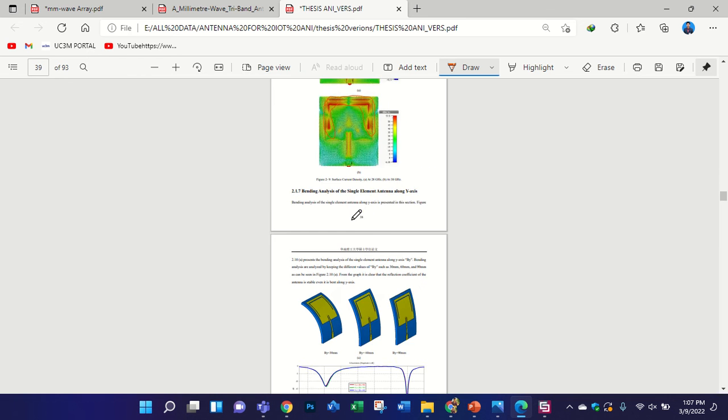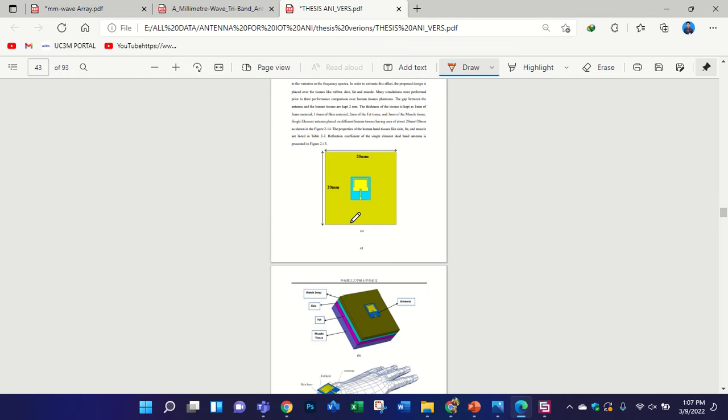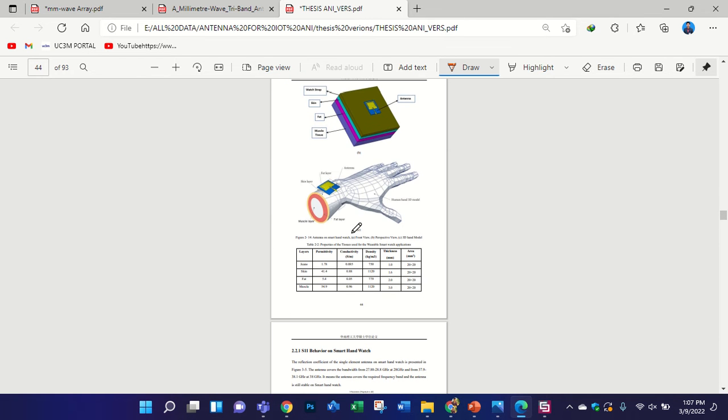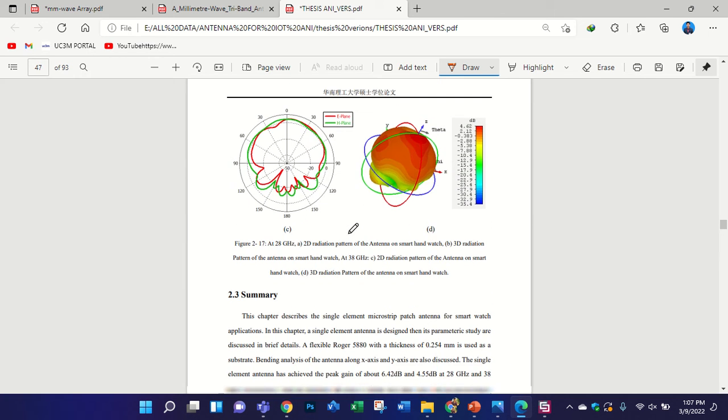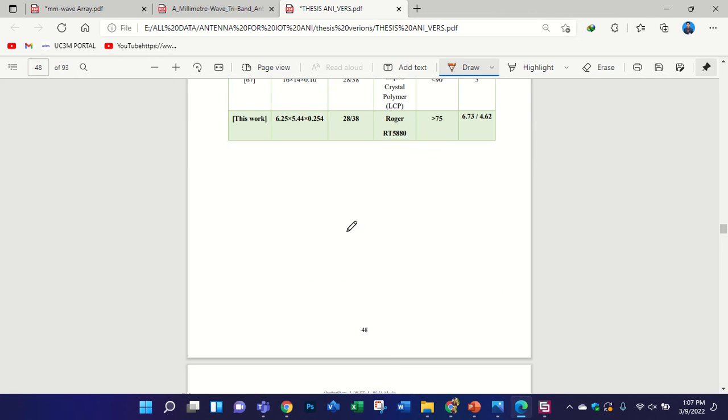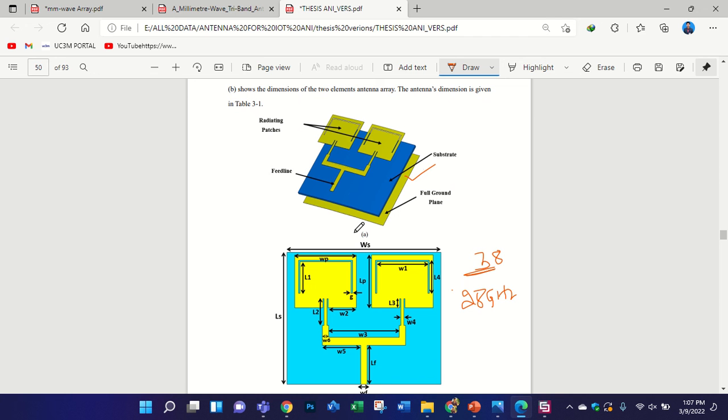You need to check the surface current, and check at which portion of the antenna it is very red. If you create a slot at that red portion, then you will notice a change in the frequency. And then you need to optimize the value of the slots.